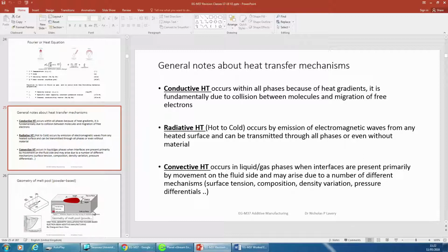So we talked about the interaction of the laser. So you've got radiation coming down, interacting with powder. There's phase change, you're melting the powder. It's going from solid to liquid, and then solidifying back into a solid. You'll have some evaporation from the metal, and that produces a condensate plume, which flows off the top and will then very unhelpfully cover the lens and inside. The evaporated metal will condense into very small particles, nanoparticles.